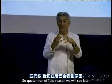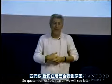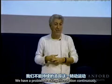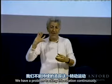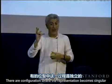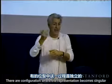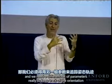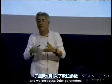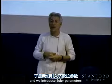The reason, we will see later, is that when we use 3 angles, we have a problem tracking this rotation continuously. There are configurations where the representation becomes singular, and we need a different set of parameters really to keep track of the orientation, and we introduce Euler parameters.